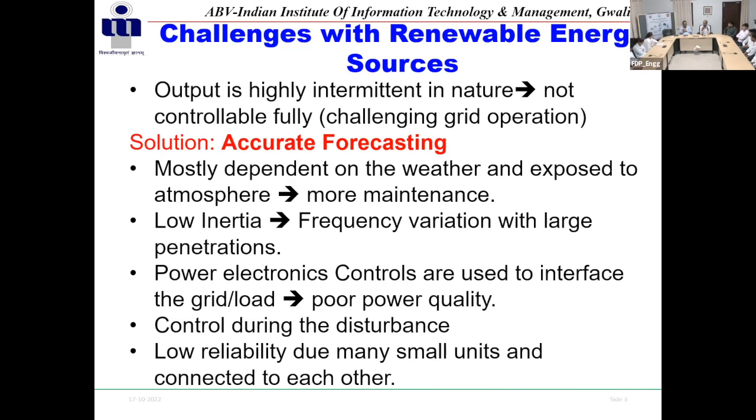So at the same time, no doubt all the load you have is switched on, and your battery is also switched on, so a huge load. And once your load increases beyond your connected load, a huge penalty will be charged by the electricity board. So a good control mechanism is required so that we should not be penalized.